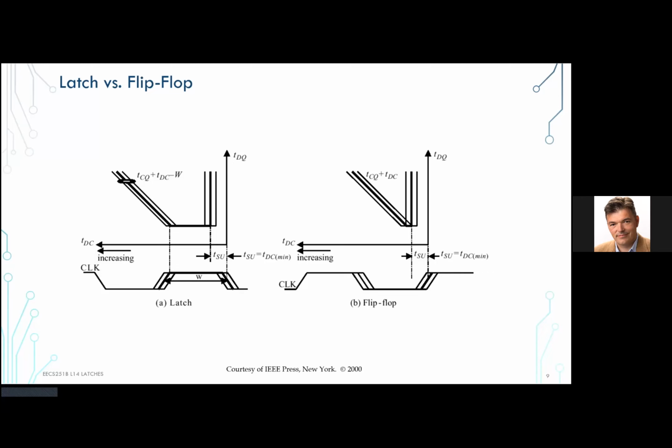In general, when you talk to these timing experts, or people who really do high performance timing and design of high performance flip-flops and latches, they'll tell you two things. One, that the flip-flop is a hard timing barrier. Latch is a soft timing barrier. That simply is, in other words, what I described last time. You can borrow timing across the latch boundary, but you cannot borrow time across the flip-flop boundary.